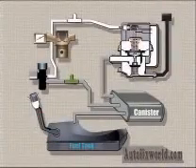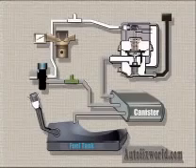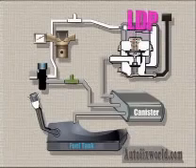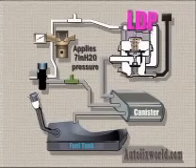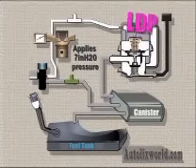The second type of onboard EVAP leak test uses pressure, not vacuum, to test for leaks. Vehicles that test for leaks this way are equipped with a vacuum-operated pressure pump, also referred to as a leak detection pump or LDP. The pressure pump operates long enough to apply a test pressure to the system of about 7 inches of water.